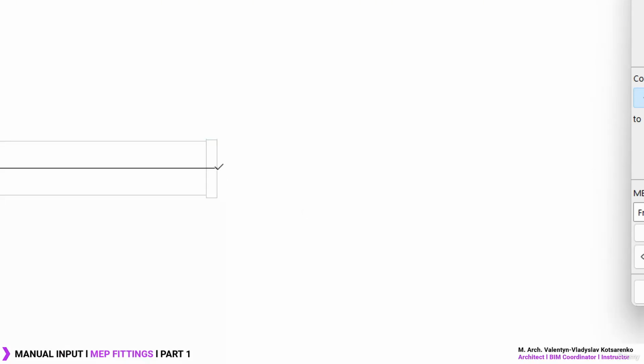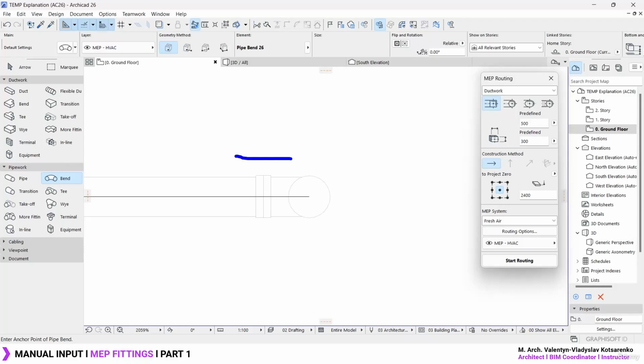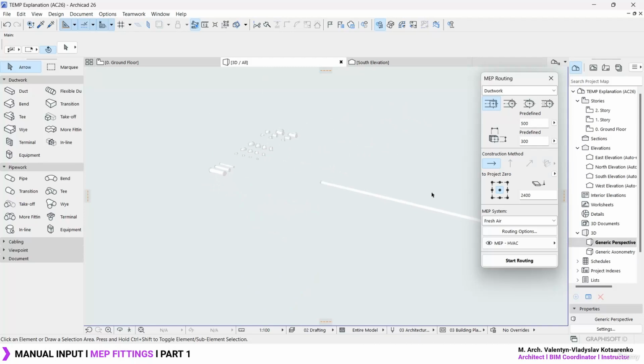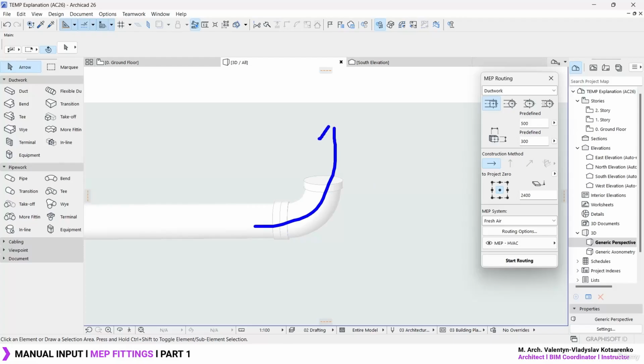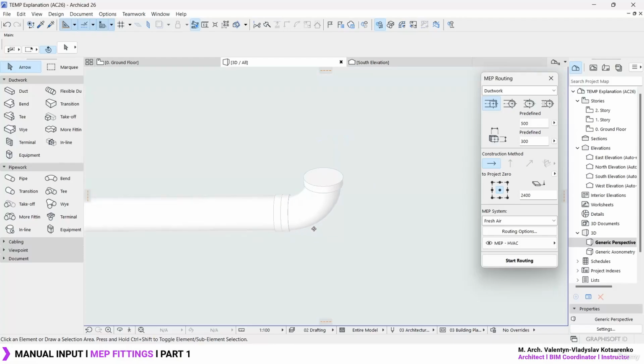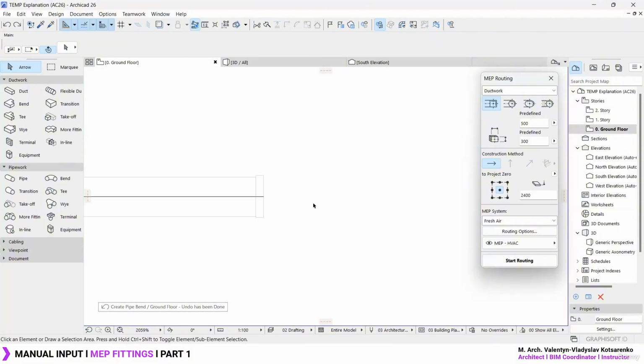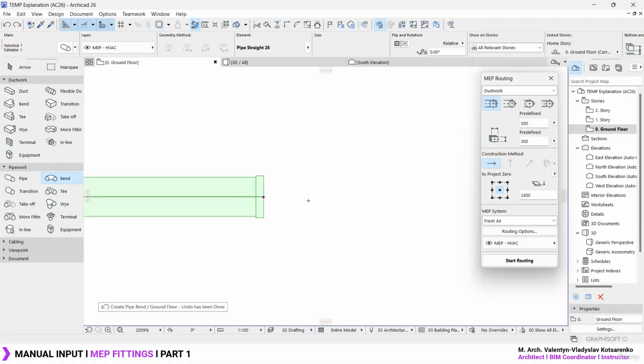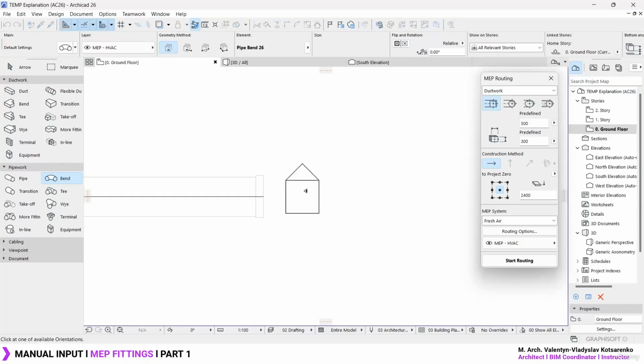Or you've got two extra symbologies. You've got one which is an X and one which is a small arrow. The small arrow indicates that the elbow is going to be positioned at 90 degrees. I think if we go over to 3D, let's see how it's been positioned. Right over here, you can notice how it's going to have a completely vertical type of orientation. Or on the other hand, if instead of using the arrow orientation, which was vertical upwards, we also can use the X orientation.